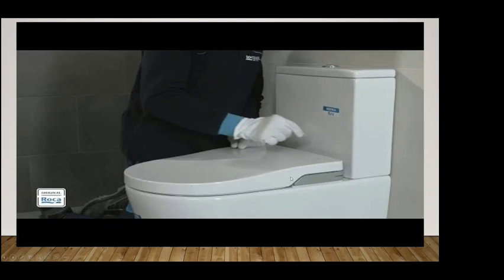So a bidet, if it's supplying water below the rim, which these things do, should technically have high level backflow protection. So it should be RPZ protected. But most of them, if they come with any backflow protection, only come with a plastic dual check that's untestable. So to install them compliantly is actually a major expense, and there's realistically not a hell of a lot to stop someone sticking one on their own toilet, even though it's technically illegal.